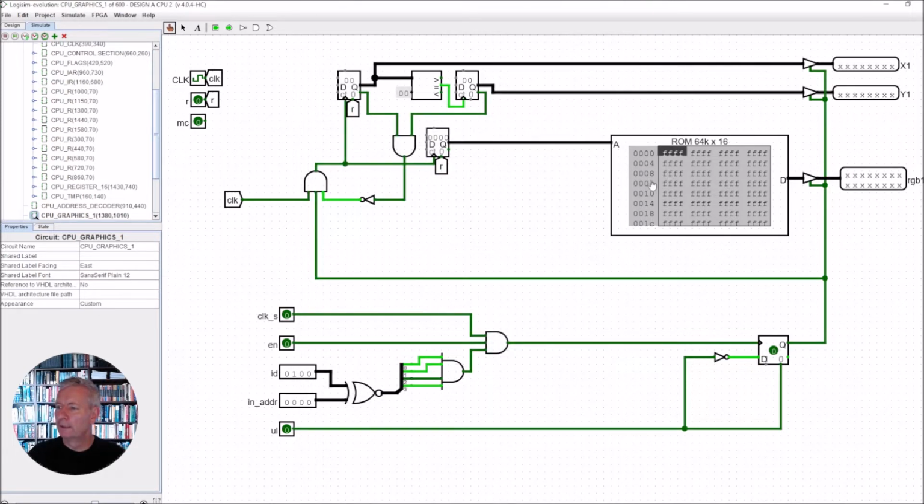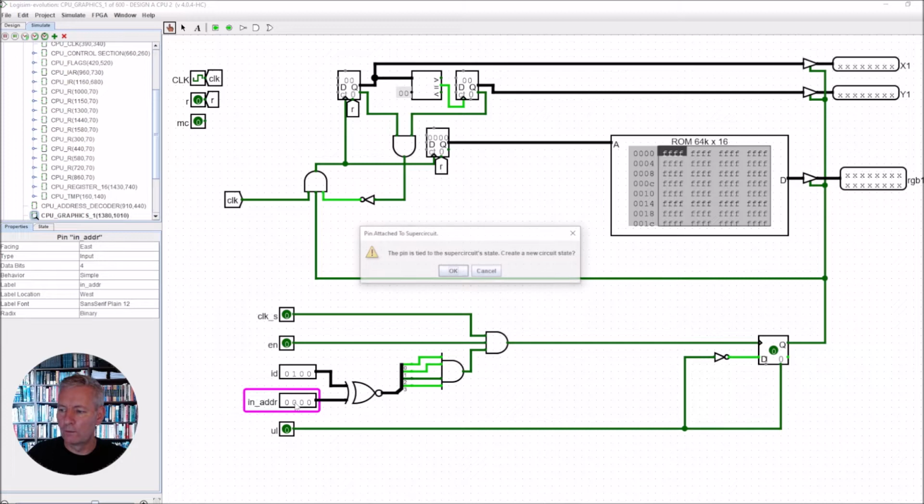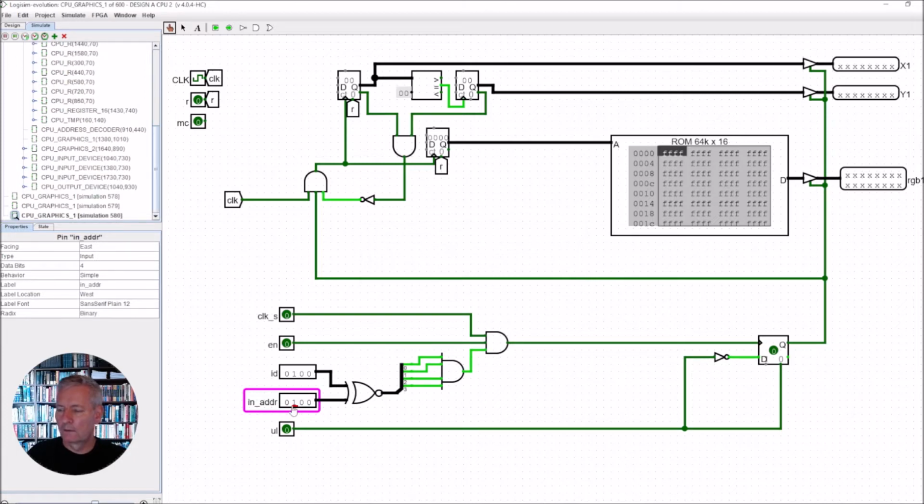What we want to do is have a command, and this new command I've generated is called splash, and it just generates a splash screen, or if you like to call it, a background image. So first of all we want to choose this graphics card. We've seen this in other videos. This graphics card is given by the value 4. So if the last digits that come in from our address bus is a value 4, then we're going to use our memory mapped IO.